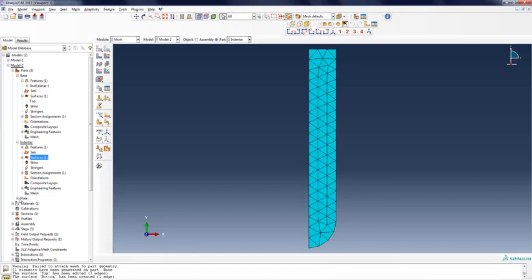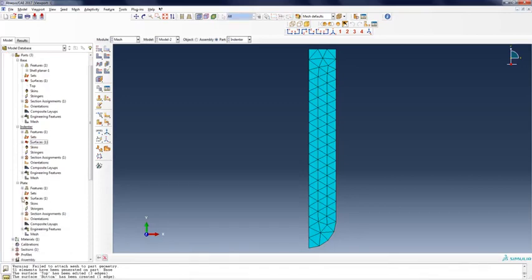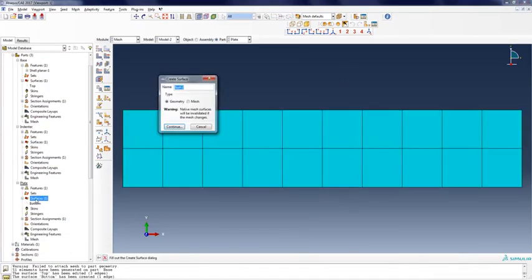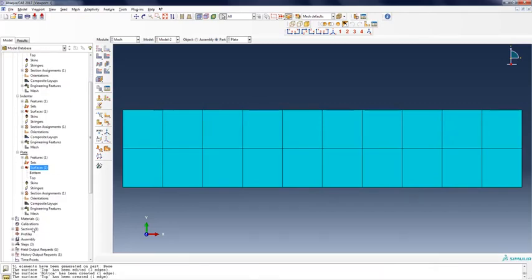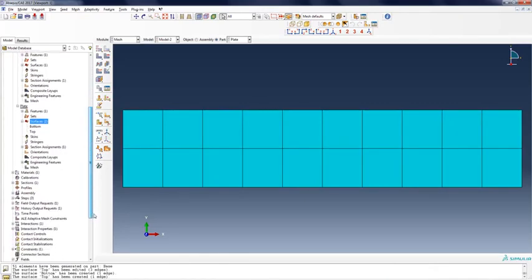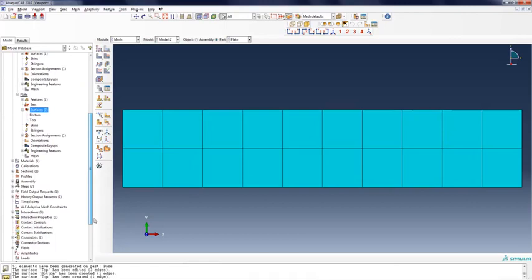And now the plate needs to include 2 surfaces, one on top and one on bottom. Previously we only had the bottom, now we also need to include the top, which comes into contact with the indenter. So we have defined all the surfaces, and we've recreated the geometry and the mesh.